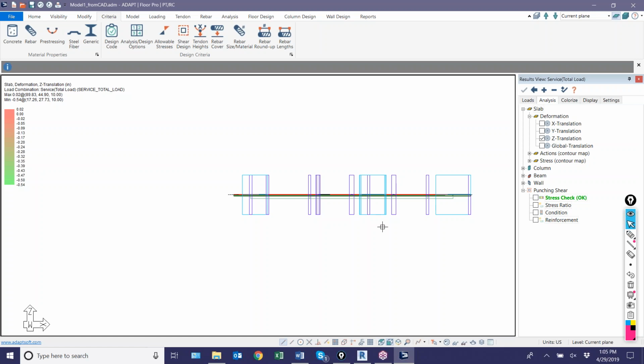So if you disregard these completely, then there's nothing there, and then you only have the bottom supports, which is released in the XY plane. Typically, the columns will still be fixed to the slab, as will the walls under the gravity load condition. If you go and you model this as a multi-story model, and then you add lateral load, then you might want the columns to be leaner only columns. In that case, you would want to release the columns. So it depends on what type of analysis you're running and for the intended purpose.